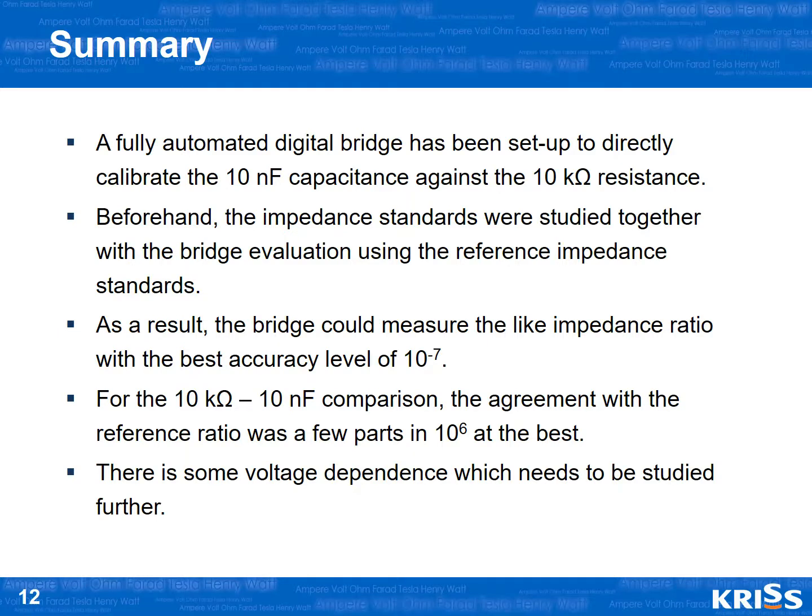The fully digital bridge was applied to measure the resistance to capacitance ratio of 10 kilo ohm to 10 nanofarad, and the agreement with the reference value was a few parts in 10 to the 6 at the best, with some voltage dependencies, which need to be studied further.